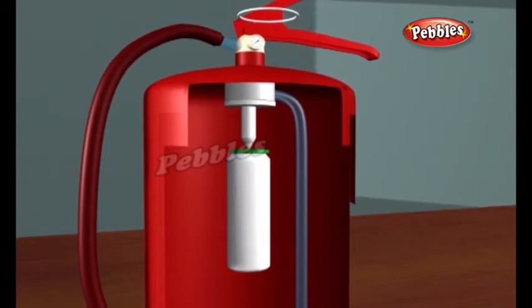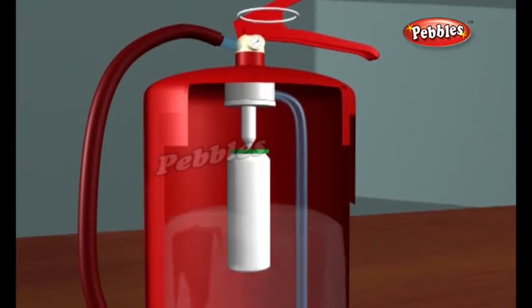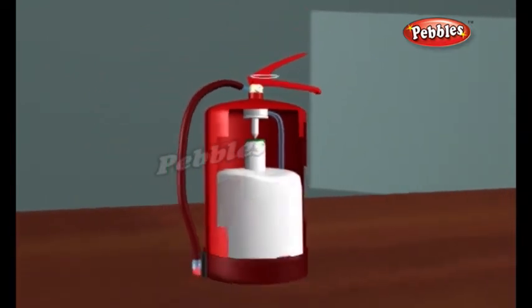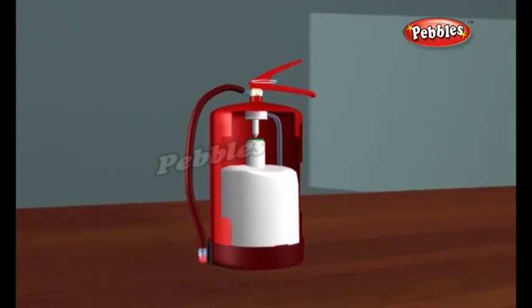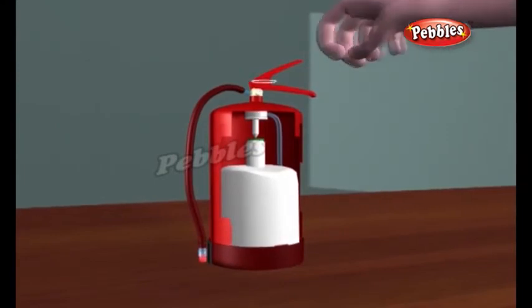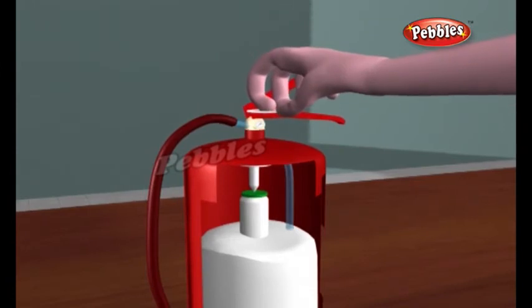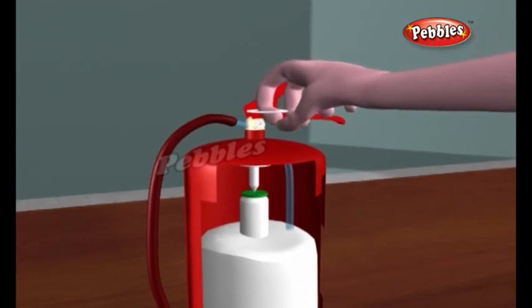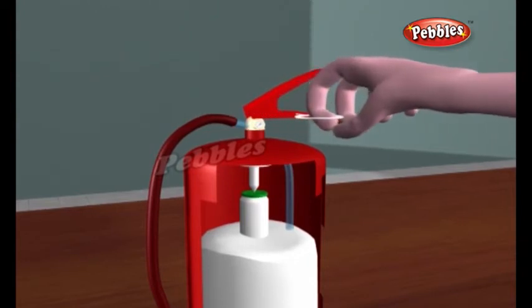Inside an extinguisher, a plastic siphon tube leads from the bottom of the fire suppressant reservoir to the top of the extinguisher. A spring-mounted valve blocks the passageway from the siphon to the nozzle. At the top of the cylinder, there is a small cylinder filled with compressed gas, liquid carbon dioxide, for example. A release valve keeps the compressed gas from escaping.